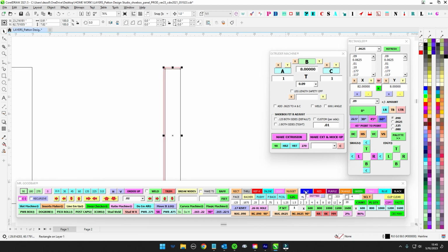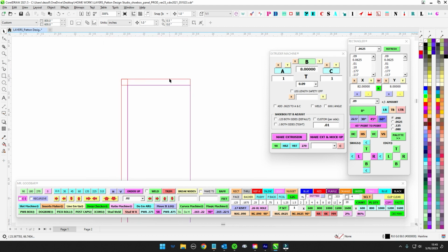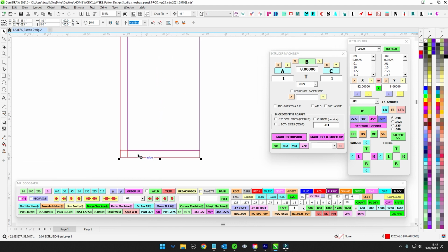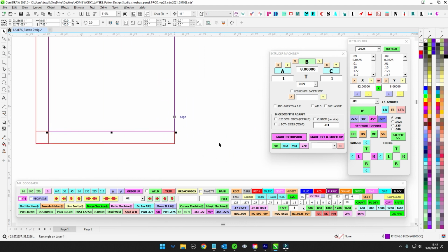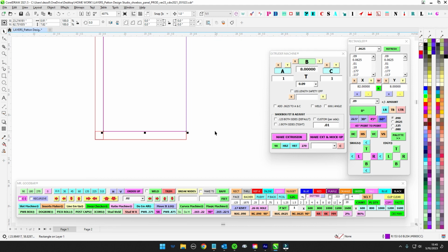So let's go ahead and make this blue. Well, let's make it purple just to start, for temporary. So when this goes to be installed, you'll have zero clearance on the top, obviously because of gravity, right? And then this is obviously way too tight because you're literally not going to have a zero clearance thing slide on. Also remember that aluminum does not slide against itself at all. It galls up, it gets sticky, it's like gummy. So if aluminum tries to slide on aluminum, it will gum up and just stick and it won't move. So you got to have plenty of clearance.